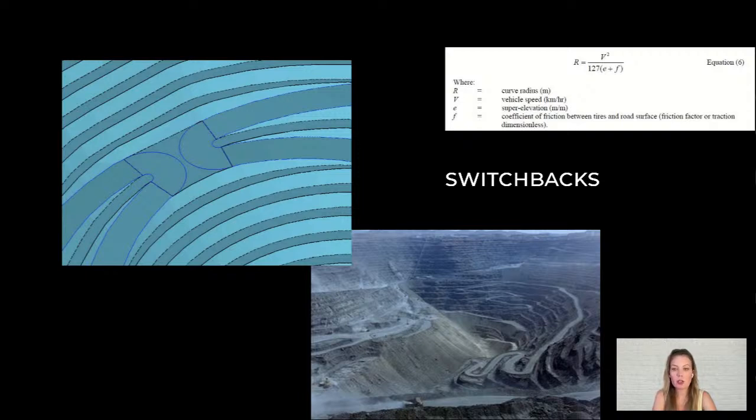When designing the turning area, it's important to place it on a horizontal intersection to ensure it has a significant radius so the largest dump truck can maneuver without crossing into an oncoming lane. To determine the required radius of the turning area, you can use the provided formula. In summary, while switchbacks are sometimes unavoidable, proper design is essential to maintain efficiency and safety.